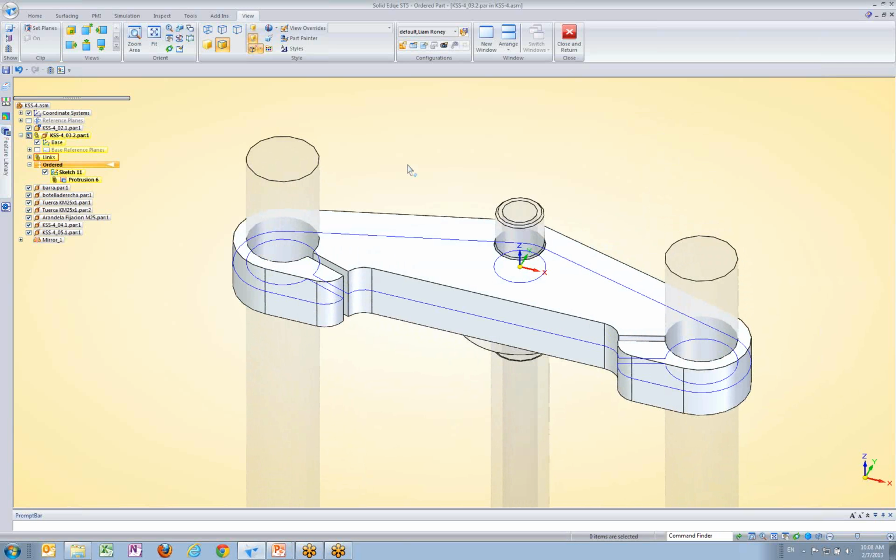So links, and anyone experienced in 3D CAD will tell you, are a mixed blessing. They give you a lot of intelligence, but they're hard to break free from. Now, Solid Edge has made some improvements in the past, making links a little easier to deal with. If we look up in my Pathfinder here, you'll see that links collect under this link thing. We can actually click on the individual links and delete them. So that makes it a little bit easier to manage. But it's still a piece of intelligence that may or may not be necessary at this point in the design.